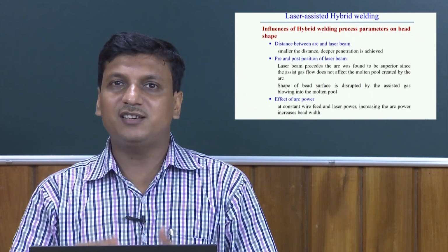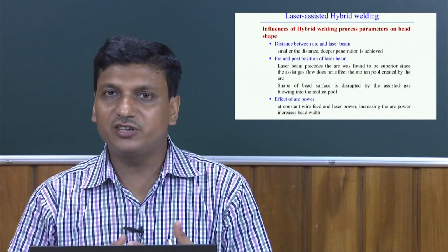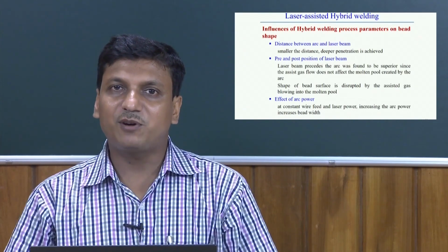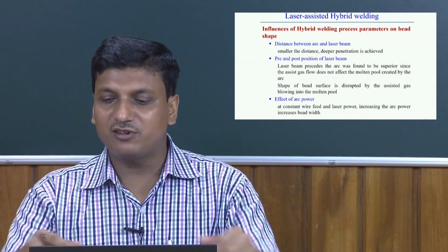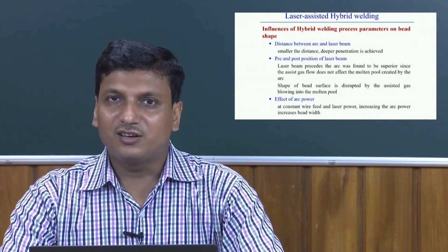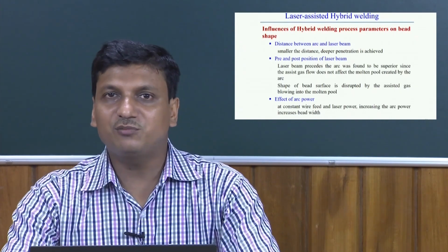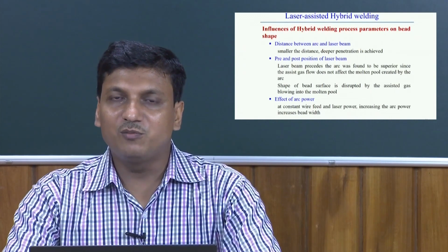And of course, the laser is used to increase the depth of penetration, and the purpose of using the arc is width. So, using the arc power, it will definitely try to create a larger weld pool on the top surface, so the weld volume will be more.